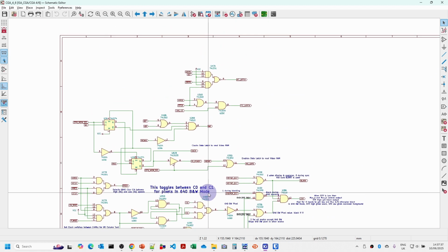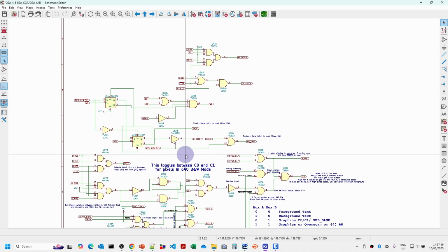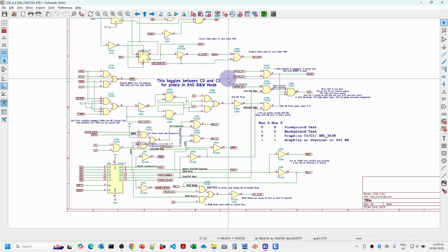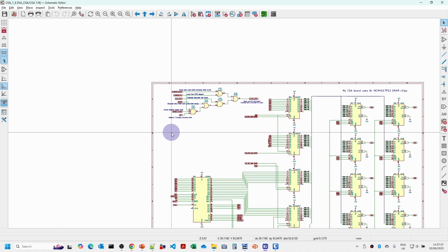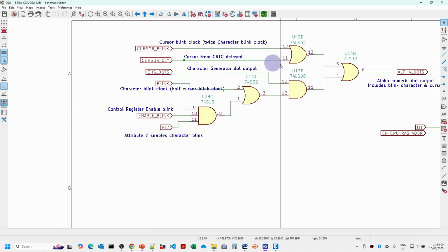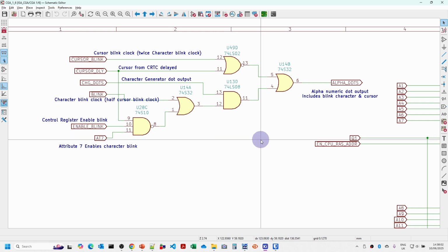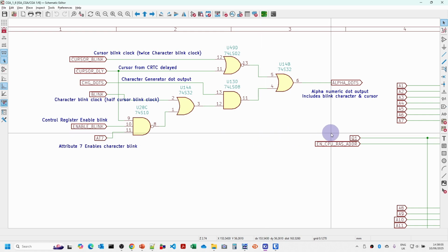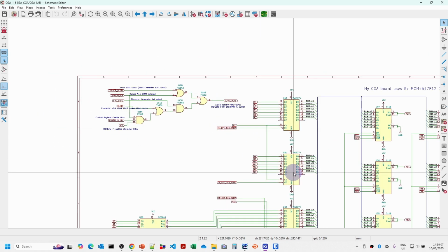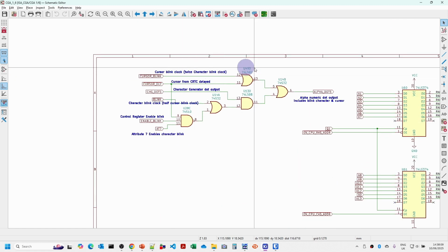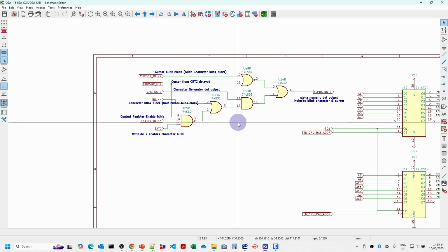There's then a number of pages of logic where various timing signals are produced, and again we'll be going through some of the logic in detail here because this determines some of the outputs for determining what video attributes and things we show. And it's a little confusing because the video attribute output is in actual fact squeezed in the top left-hand corner of this diagram, which is the main one with the video RAM and the CRT-C. So this little bit gets snuck in the corner here. But we'll be going through this in a little bit of detail.